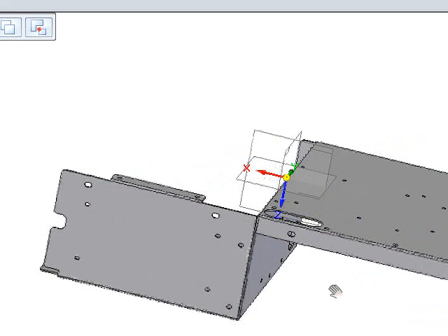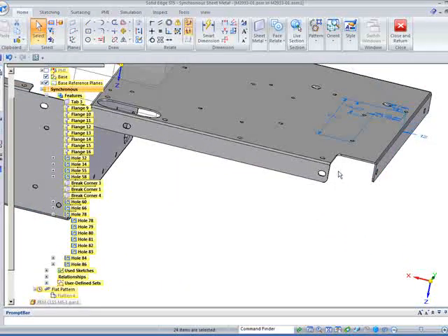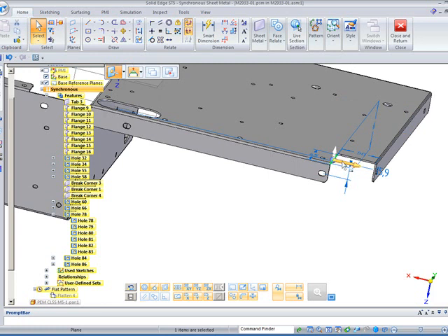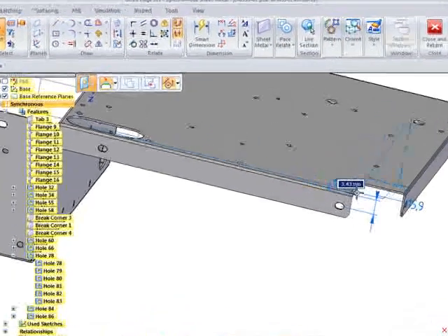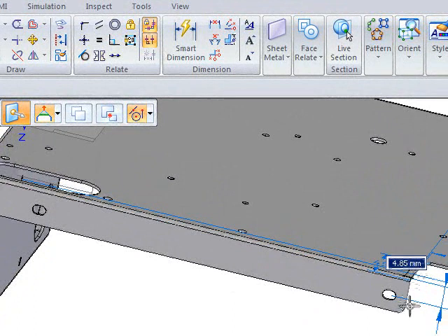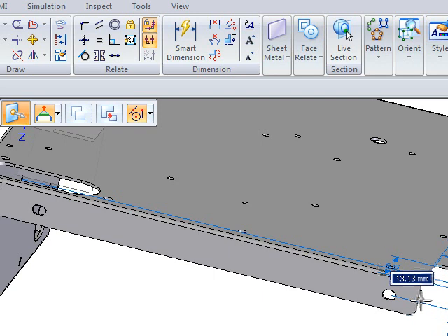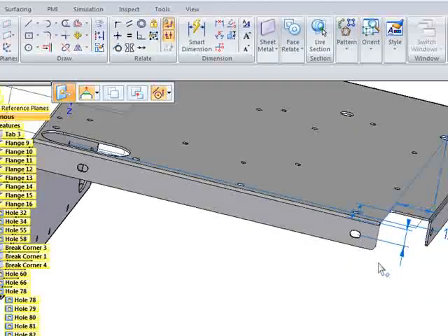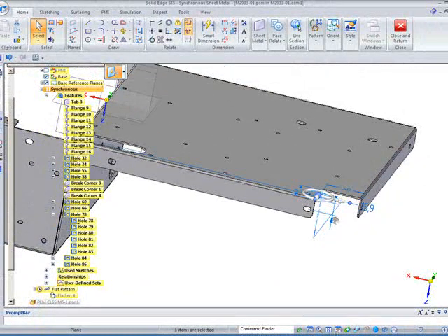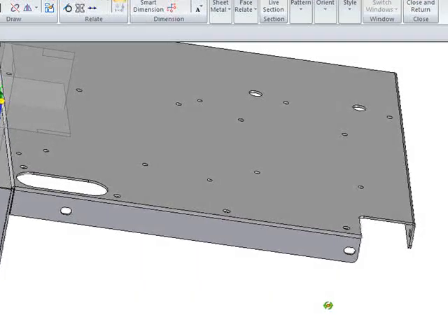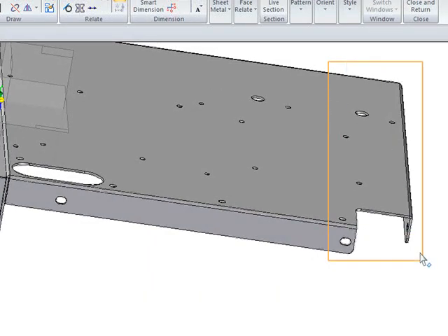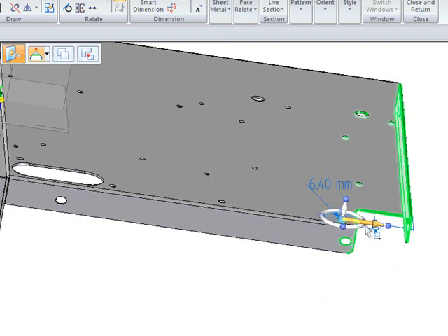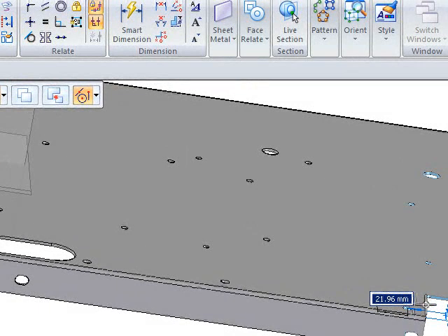if we wanted to rotate this around, we could look at maybe just this face here, and we can adjust the depth of that. Notice, because we've got a continuous face here, it's pulling in that side area as well. So it still has some options in there. And then if we wanted to maintain that depth, we could just do a fence selection around all of these items and drag them all together, so we can maintain this cutout on the side along with the holes.